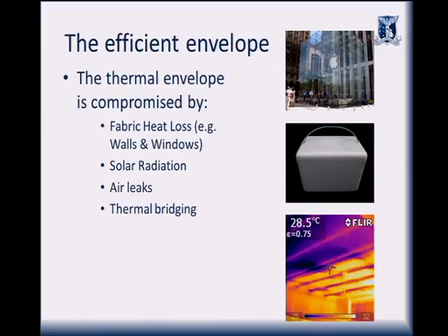So where's the insulation missing then? Okay, where it's purple. So over here, they're the roof rafters going across there, supporting the ceiling. There's no insulation in that top purple section. So what the camera sees is that the plaster is colder because the heat's just leaking straight through.